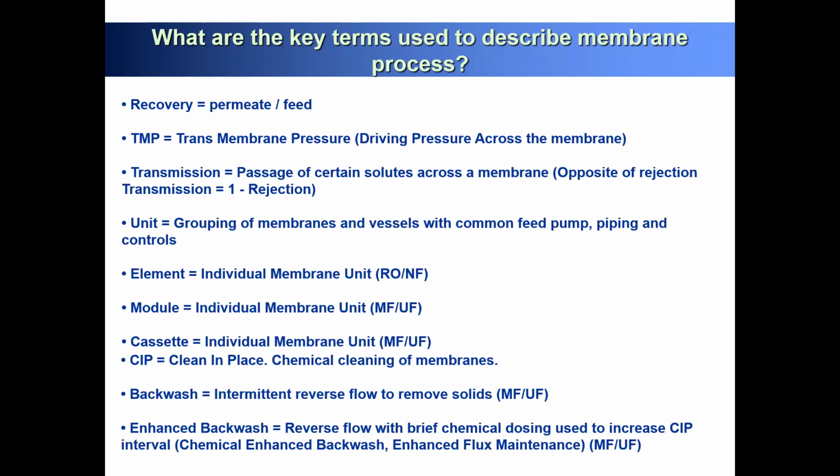So when you design your ultrafiltration assignment, you have to consider backwashing time. I want to operate 1 hour, then backwash 1 minute. So that's how you can consider the manual of your ultrafiltration and microfiltration membrane. Also, backwashing can be achieved with different chemical dosing.